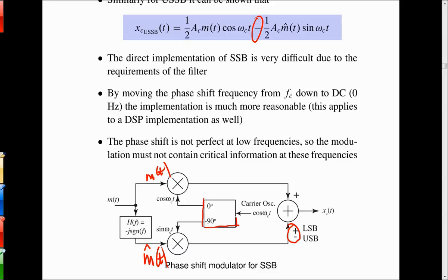And for microwave circuits fans, this is the quadrature hybrid that you learn about if you study RF circuits. That's just a component that a microwave circuit designer can build. You can buy it off the shelf for your design. When I worked at Motorola, we bought them from a vendor and put them right on the circuit boards. But it's an element that has very precise control over the phase shift, called the quadrature hybrid or 90-degree hybrid.